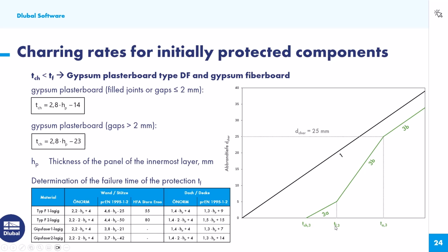And the Eurocode 5 does not say anything about it. Okay, it says something in Annex C, to get the values from tests. Of course, this will not help us engineers. So in this case, we have to look in other approvals or in other codes. For example, the ÖNorm from Austria, they provide values for type F.